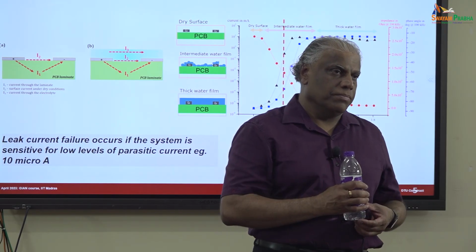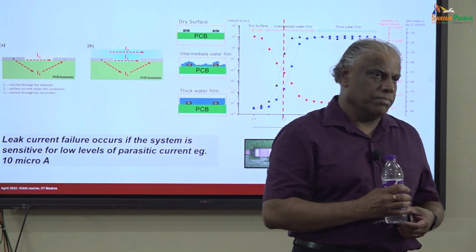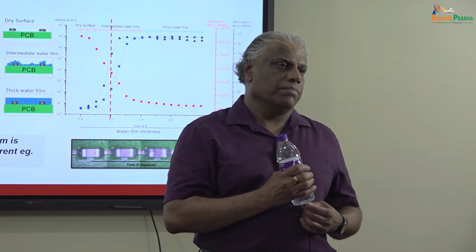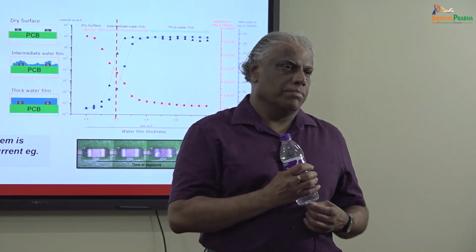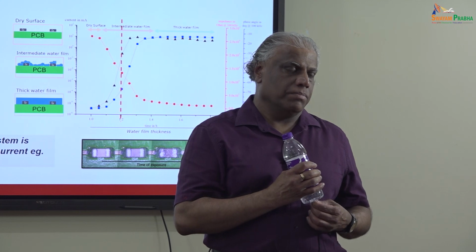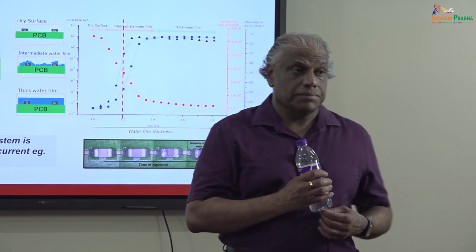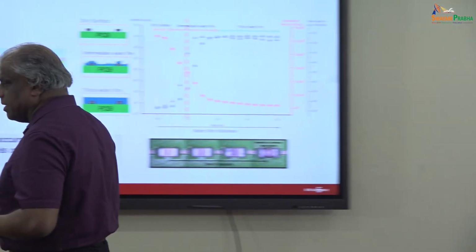In normal corrosion experiments, from the EIS we fit an electrical equivalent circuit and get the circuit elements. So we are not worrying about any current. So here from the EIS, are you getting leak current from the EIS test? Leak current is from the DC experiment.